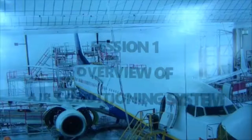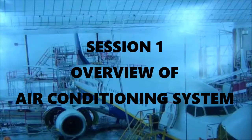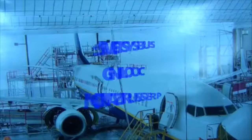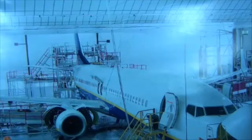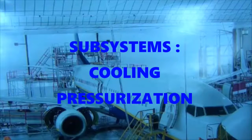The air conditioning system. Okay, think about 2 concepts or functions: cooling and pressurization, because that's what the air conditioning system is involving. So there are different subsystems, but as a general overview, just think of 2 different ideas, and that's the cooling of bleed air coming from the pneumatic system, and then you have pressurization of the fuselage.